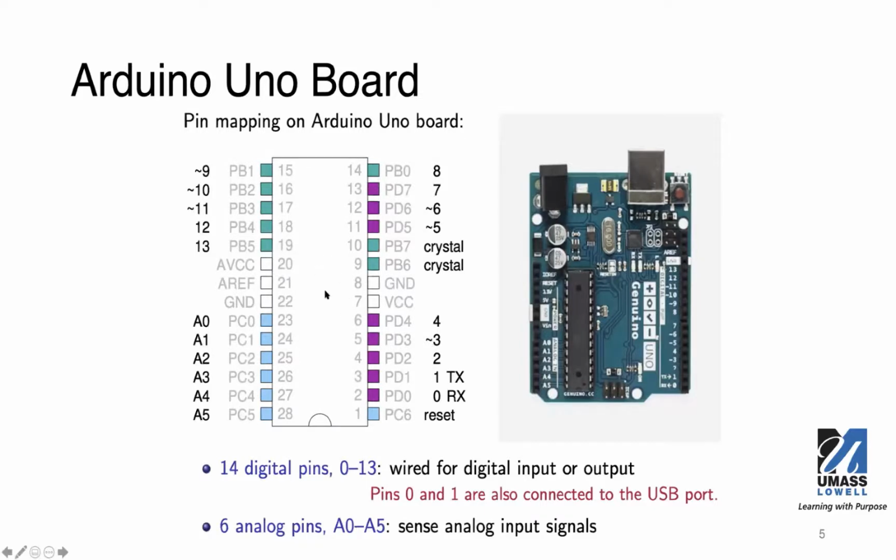So once you have this chip put onto an Arduino board, and this is the one that I used from last class, this Arduino Uno board. The individual pins are routed to these connectors. And the numbers do not match exactly, but this diagram shows how these different ports are mapped to the pin numbers on the socket, so on these two sockets.